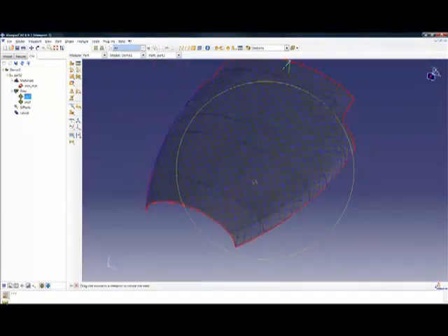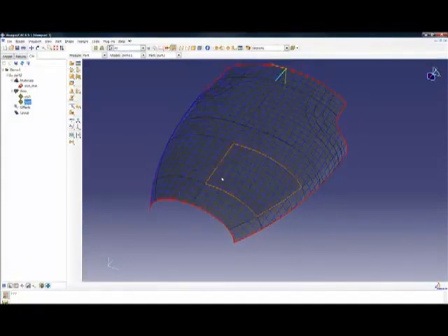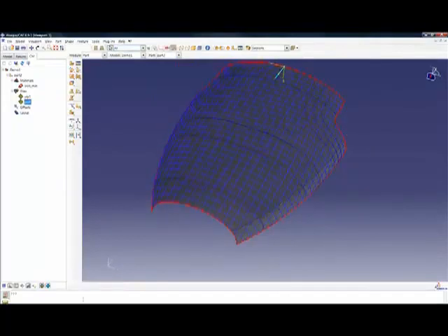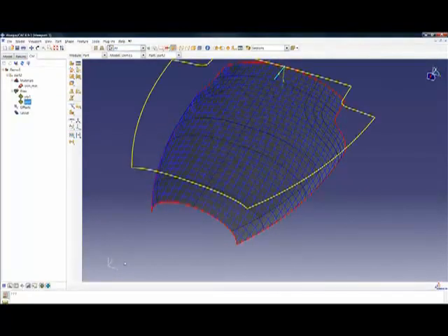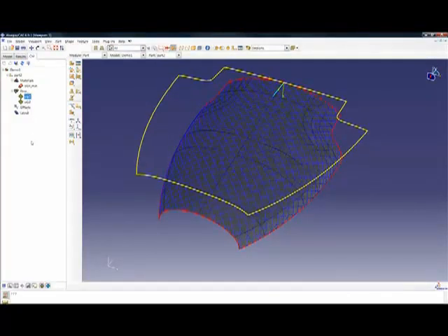We turn off the individual elements and just look at the fibre visualization, and we'll be switching back to the 0-degree ply again just for visual reference. And also we can switch on the display of the flat pattern, which is created and stored with the layout file as well.